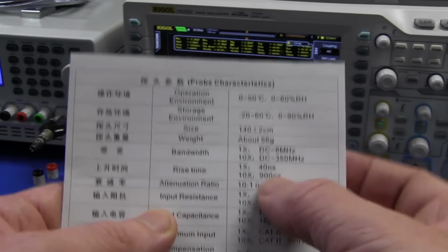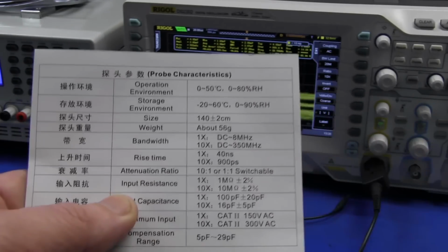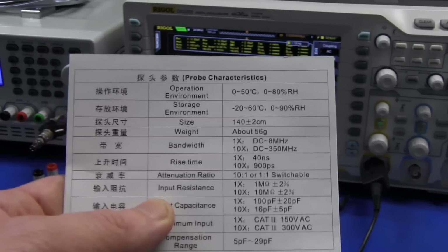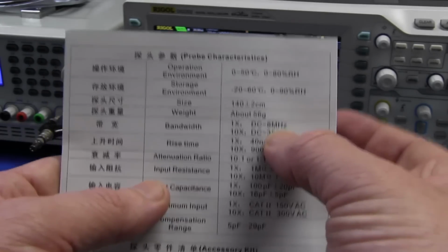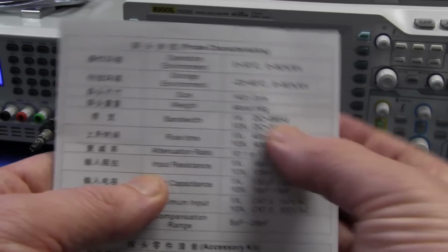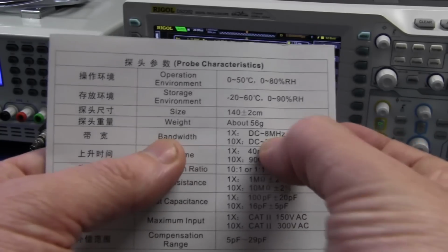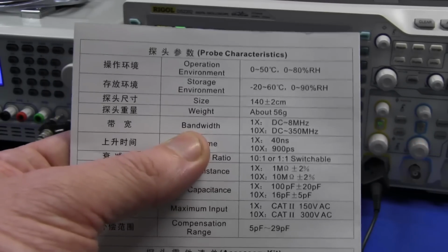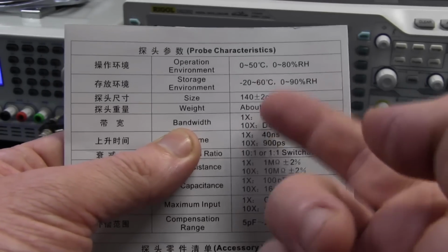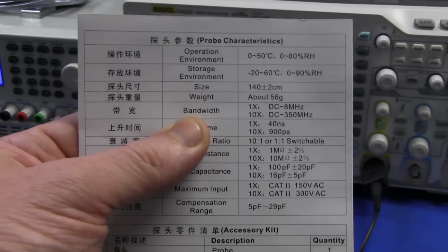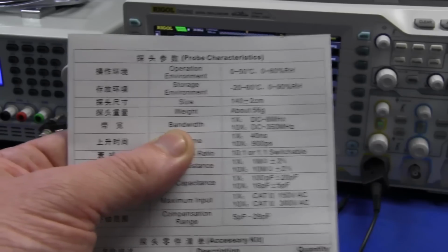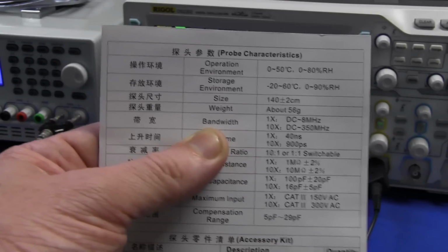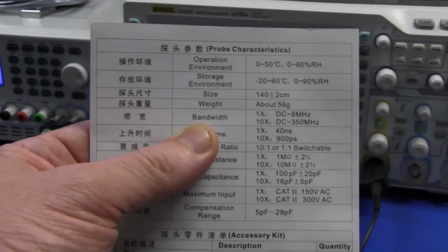I won't go into it, that's a whole separate video, but ×10 probes, that's why they're used, is because they are higher bandwidth. So effectively, we've gone from that 20 meg filtering on our scope to an 8 megahertz bandwidth filtering, and that's why our ×1 probe is actually going to give us a lower noise measurement because it's bandwidth limited. So all that high frequency noise, wherever it's coming from, is being attenuated.